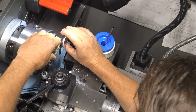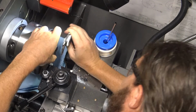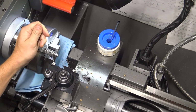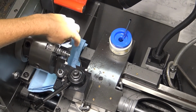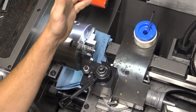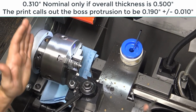So I should have a diameter of 375 here, and I'm at 376, which is fine because we have a 5 thou tolerance on either side. So my boss is the correct size. Now I just want to measure my shoulder, the big part of the flywheel, which, if we look at our print, should be 0.31 or 310 thousandths, because our part's half inch.